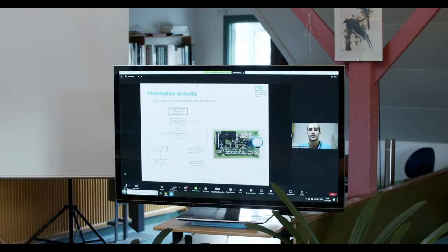If we go out of this range, the generator must be braked, so it's short-circuited by a relay and protection activates. Batteries are disconnected from the circuit. It's very important to short-circuit this generator. When we disconnect the batteries, the load disappears from the scheme. So the generator starts to spin faster and faster with strong winds and can cause mechanical issues.